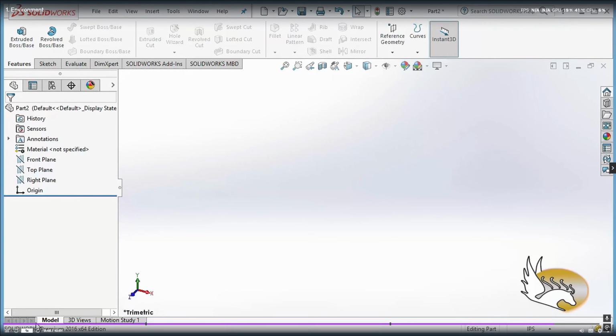On the bottom side of this environment, the only thing that is very important is the units button here. You can see right now the IPS units, which is inch, pound, and second. That's the active units for my environment. So whenever I type in a number, that's going to be either the distance in inches, the weight in pounds, or the time in seconds.